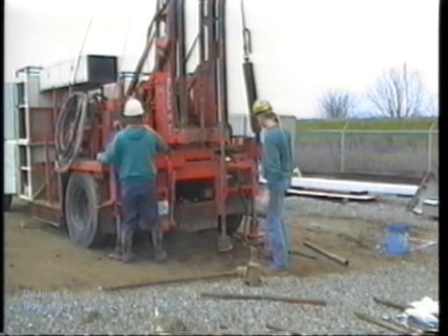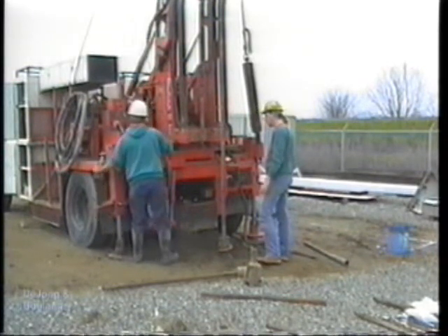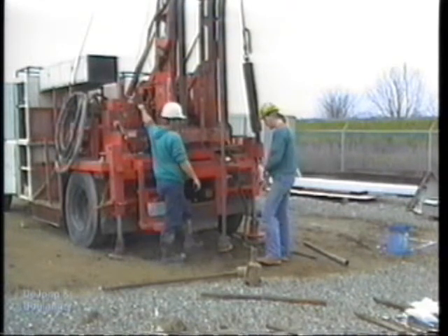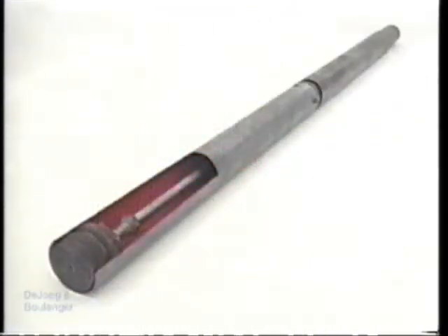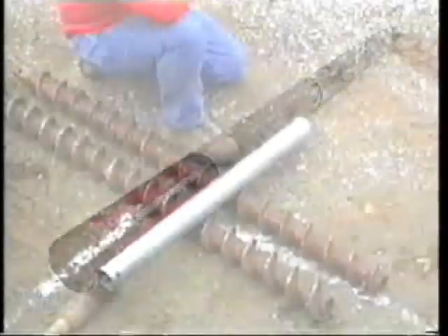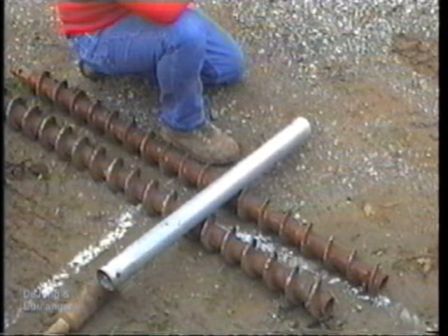These conditions can be greatly improved by using a piston to close the lower end of the tube until the sampler has been firmly positioned against the undisturbed soils at the bottom of the borehole. The piston is then held at this elevation, in contact with the soil, while the tube is advanced around the piston and into the soil. Initially, the presence of the piston prevents soil from rising into the tube faster than the tube's penetration rate. Later on, downward movement of the soil sample is resisted by a vacuum that develops between the piston and the top of the sample. After the sampling tube has been advanced, the piston is fixed in its new position with respect to the tube. Both elements are rotated to separate the sample from the underlying soil, and the piston and tube are removed from the hole.